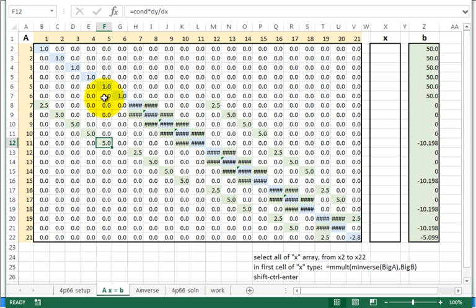So when I evaluate that coefficient, what was that coefficient again? Hit it. It's right here. Conductivity times dy divided by dx. Wasn't that the coefficient in front of T5? And then over here, what's the coefficient in front of T10? Conductivity times dx divided by dy. So I have it so I can read it. I can debug it. All right. And then over here I have the T infinity times dl times convection with the minus sign. True? All right.